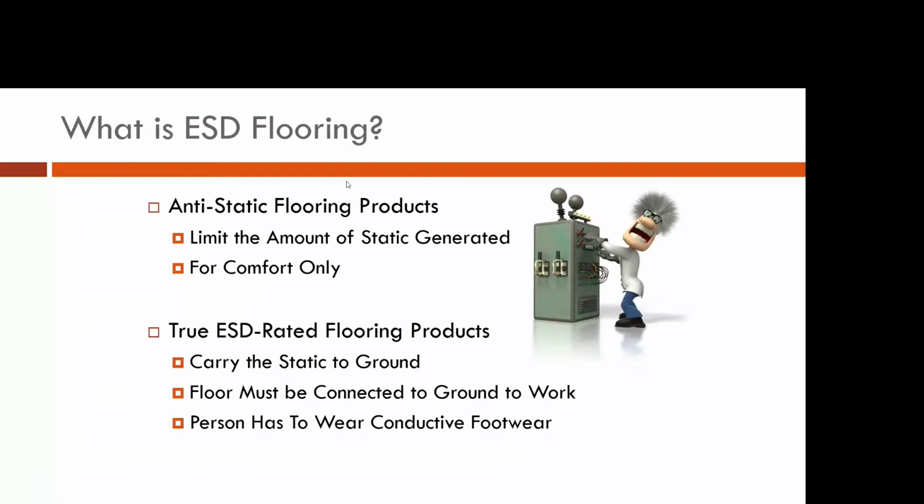A true ESD floor has a connected path to ground. So an ESD floor starts out as an anti-static floor because it will reduce the amount of triboelectric charge built up on it. But then it becomes a full-blown ESD floor when it has a path to ground. Then it's doing its job of removing the charge off the operator or the person walking on the floor, and takes that charge to ground.